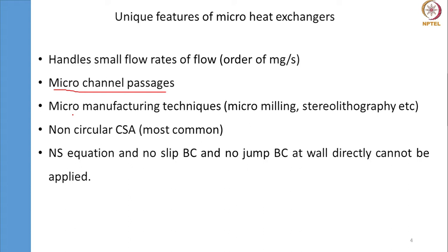Coming to the heat transfer and pressure drop perspective, we cannot directly apply Navier-Stokes equation when we have a micro channel flow. Also, there are two more important boundary conditions. First is the no slip boundary condition, which is true for conventional flow.